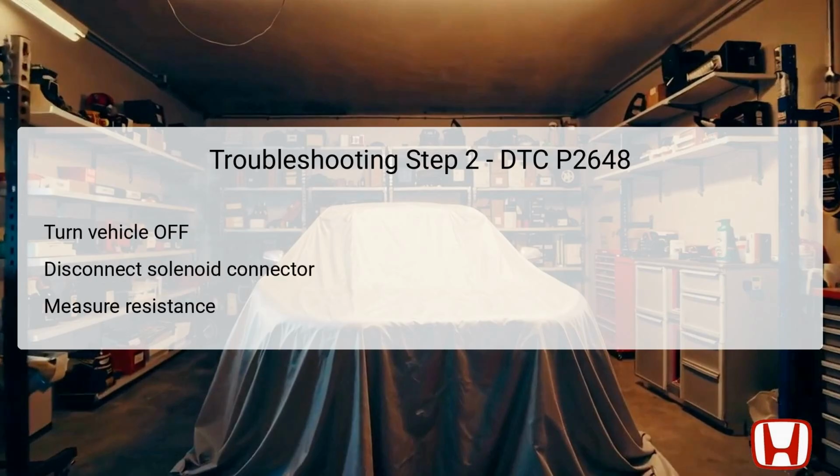In the second step of troubleshooting DTC P2648, turn the vehicle off and ensure that it is secured in the lock mode.